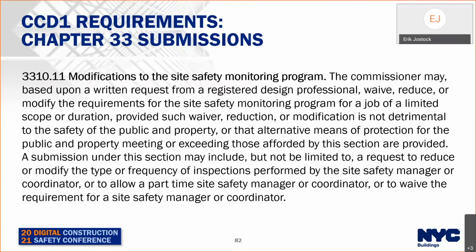So it's important to remember that a practical difficulty of complying with the code must be demonstrated. Reduction in site safety oversight is often requested out of convenience or budget reasons, and the department does not accept that as a practical difficulty. For this section, the department used to get many CCD1 requests to reduce site safety manager coverage on facade jobs to 2 hours per day. There was a facade rule that addressed this by allowing a qualified person for site safety, or QPSS, to be designated to oversee the day-to-day operations, with a site safety manager designated on the permit and only required to be present at the site for specific types of work, like installation or removal of supported scaffold, or mast climber. So we don't see as many of those types of requests anymore, but practical difficulty, can't stress that enough.